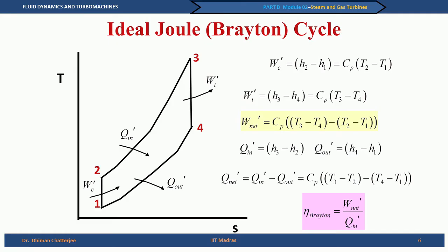So, this gives us the thermodynamic background of the gas and steam turbines, which we are going to discuss now. And also let me make one point clear, that when we discuss the steam turbine, I will talk with reference to steam turbines, but I am not really considering wet steam. So, my approximation for this work is that I am considering the steam also to behave like a gas, which is possible approximately when we are talking about the superheated zone. In the superheated zone, the steam can be also considered as a gas with the equivalent properties.